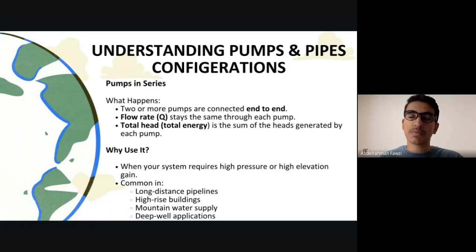Because as we mentioned before, if you have a long pipeline system, this means that you are dealing with lots of friction, and then you need to compensate this huge amount of friction with big heads like these series configurations, and also the high-rise buildings. You need lots of head, lots of energy to produce. So you're going to use this series configuration.